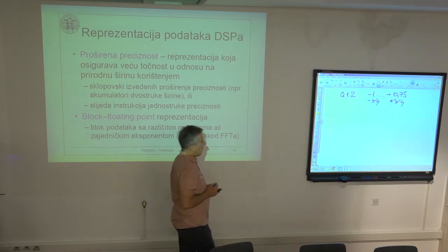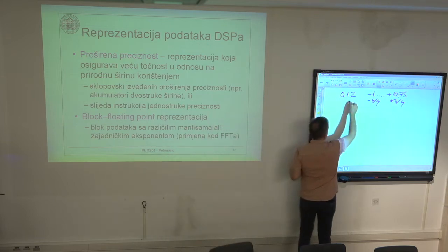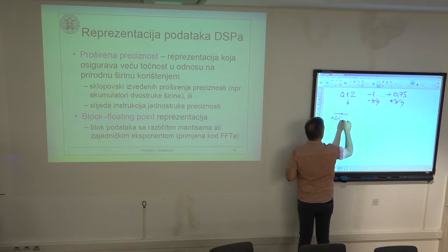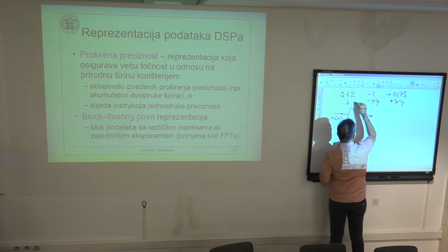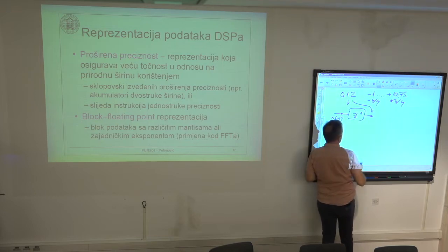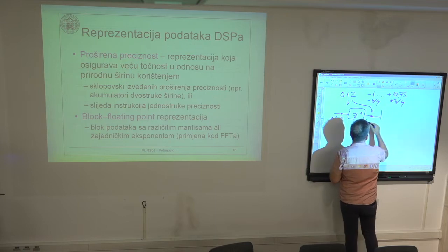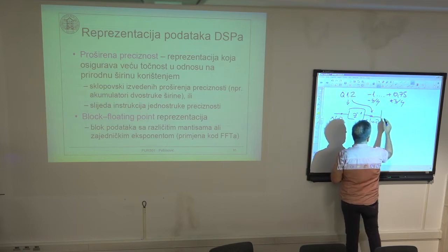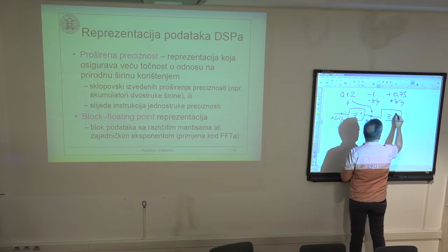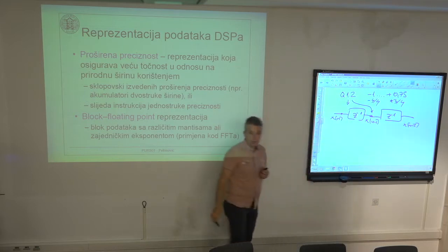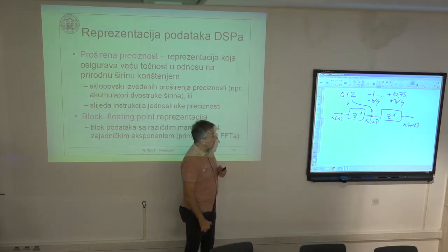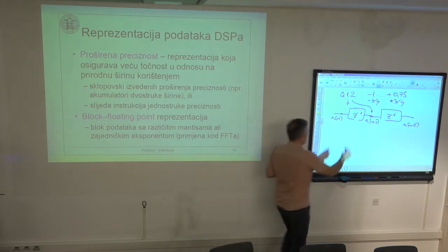So if I have such a representation for the signal x[n], this signal is delayed here, so the same Q1.2 representation is here as well. This is x[n-1], the previous input sample, or x[n-2], the sample 2 steps before. These values are multiplied by coefficients.